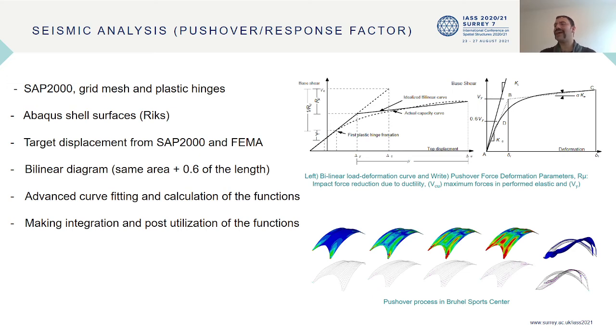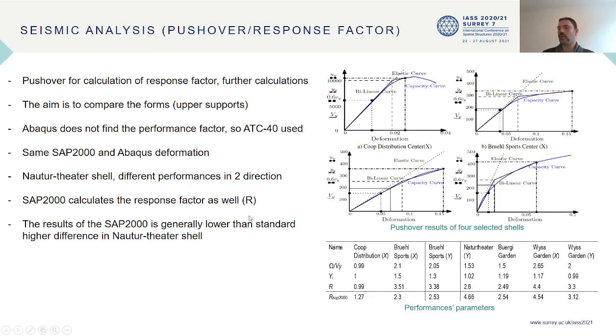For that, I developed a specific function for each pushover diagram to be able to find these bilinear elements. So up to now, in addition to evaluating the shells under pushover analysis, we also have some functions related to each pushover diagram, which will be referred to again later.